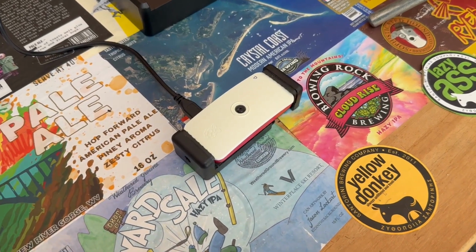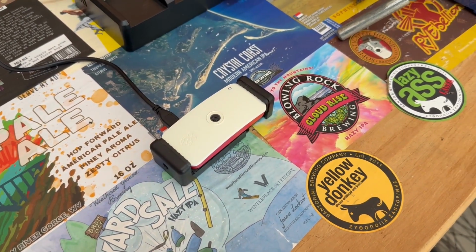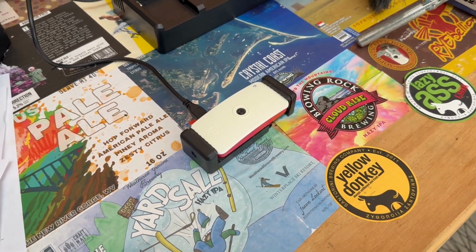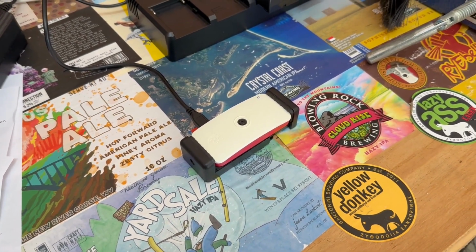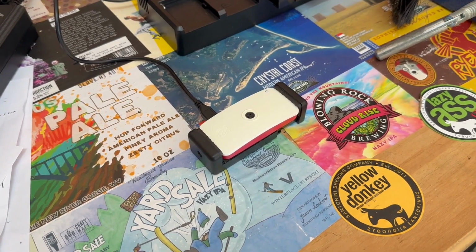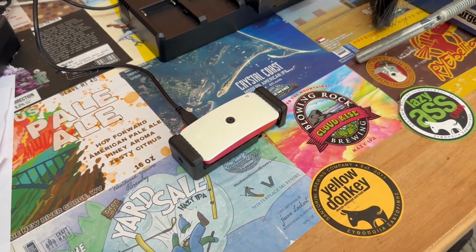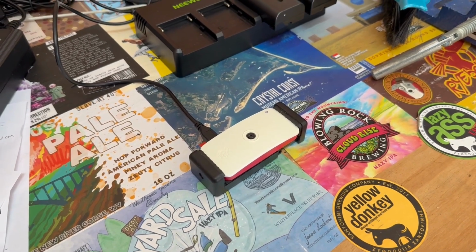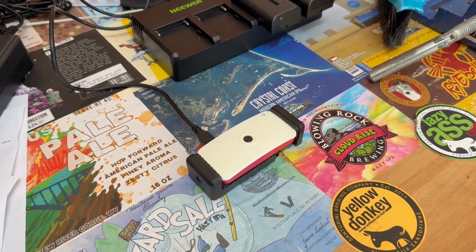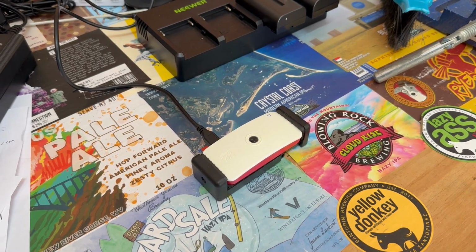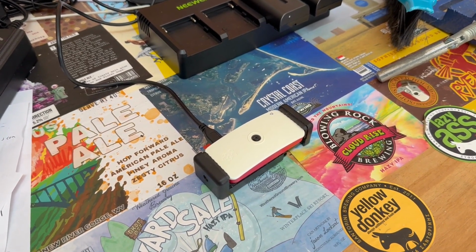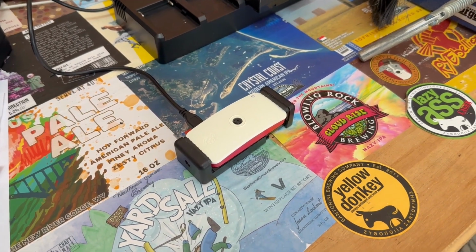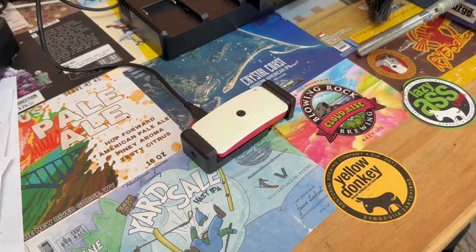The reason that I am testing like this is because typically right when you install it without changing anything, you would need to go into the web browser and click motion detection start. But what we did is we changed the config file so that whenever you plug it in, motion detection starts automatically. So when it boots up down here, it's just booting up on its own and it's going to start motion detection. So it's going to just immediately start recording anytime it sees motion.